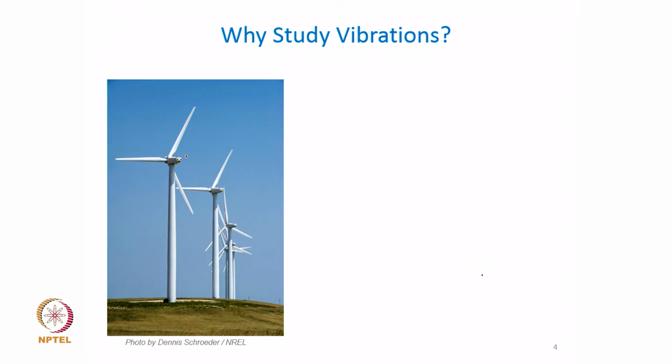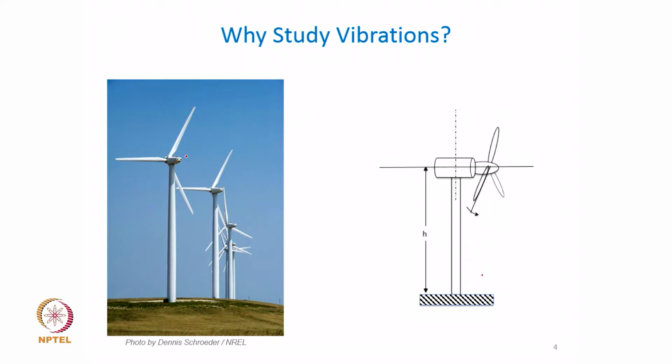And if we want to design the column of this wind turbine, the basic process which we already have learned through the first course in mechanics or solid mechanics, strength of material to be precise, is making a small model of this wind turbine like a column, as you can see here, and sitting at the top is the nacelle which you see here, and then look at how the sizing of this column will be based on the weight of this particular element, the nacelle.